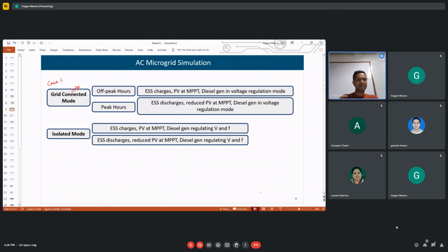So this is a good advantage: because of this we have galvanic isolation. Another advantage is that bidirectional power flow is possible with high power feeding capability. And large conversion ratios are also possible with the dual active bridge. With simple non-isolated converters, which are buck and boost, the conversion ratio is limited to a maximum of 4.